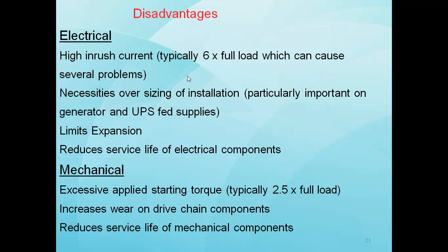So what are the disadvantages? The disadvantage is high inrush current. It is 6 times the full load current, and it causes severe problems. Next, it necessitates over-sizing of the installation.